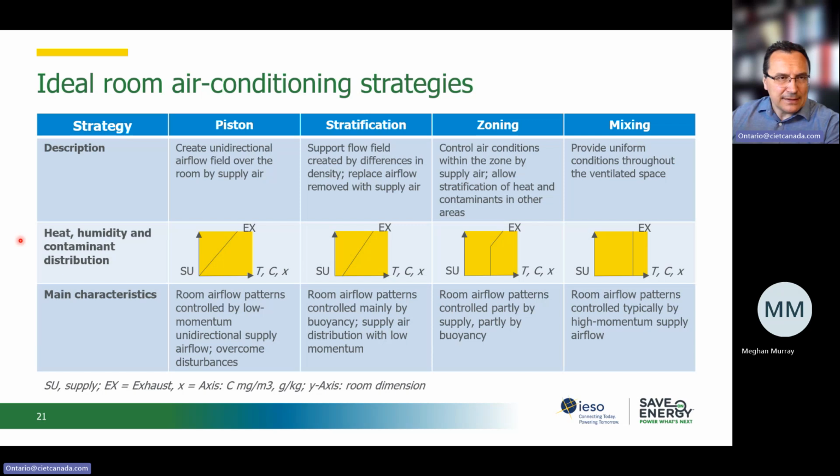We have various strategies that we implement in the space: piston type of distribution, stratification, relying on the density of the air at various temperatures to transfer this contaminant, zoning by applying a local control, and then mixing, which is basically providing uniform conditions throughout the entire ventilating space.